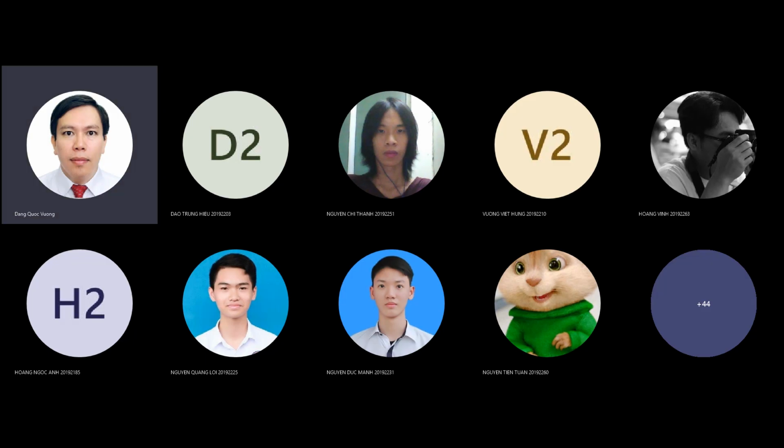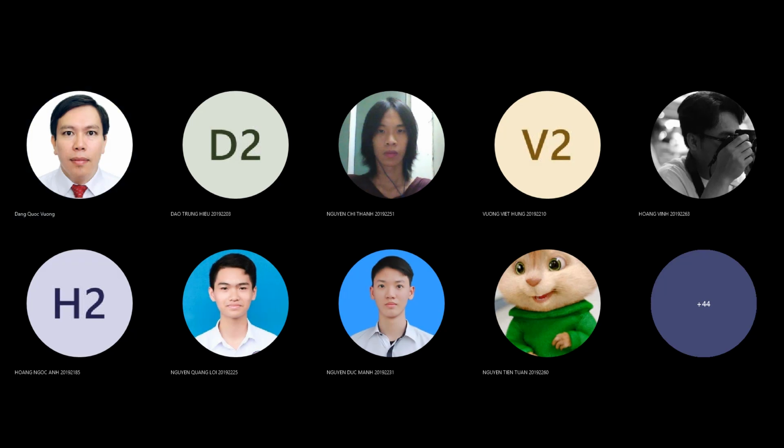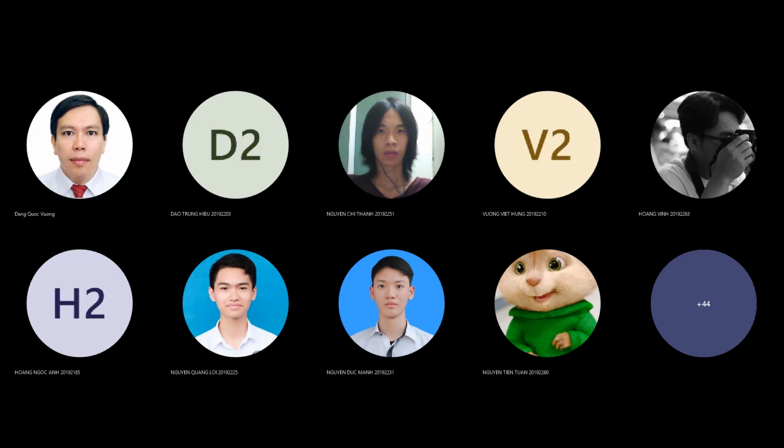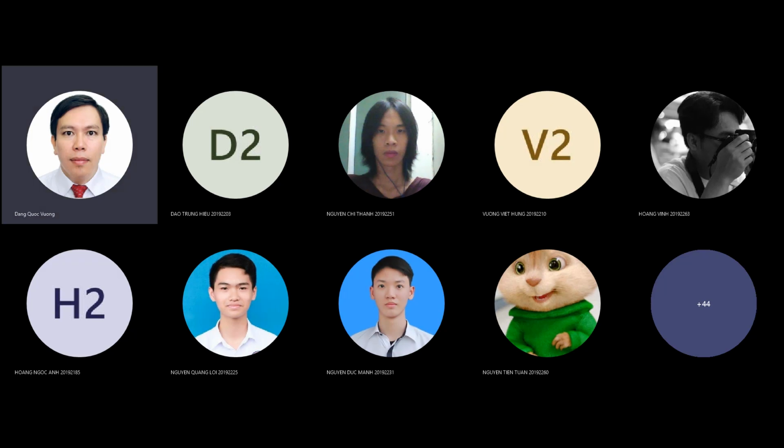Of course, if I change anything here, we get number 6 or number 4 or number 2, but not number 5 or number 11 or number 9. Why? Because it's the same connection, star and star, and the number here must be an even number. I think you understand what I'm saying.